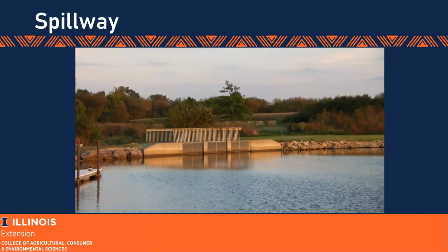Here's another structure. It's a little bit larger, same general concept. This one has a watershed area flowing into it, a little bit of a natural stream flowing into it. Unique from a design standpoint, if you notice the trees and the brush behind the open area there and to the right-hand side, that's actually a stream that the water from this would naturally have flowed into. So rather than intercepting that stream, they actually built it off to the side of it and dammed up along the edge of the stream to create the pond.